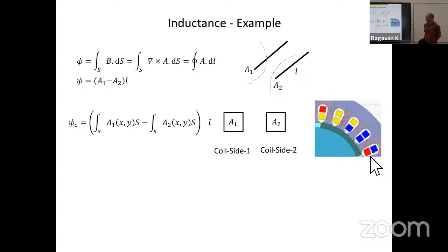Similarly, in an FEA solver, you don't have access to what the solver is doing. It's a commercial package, and you are not generally going into the background code telling it what to do and what not to do, right? What I have seen is that people think the inductance that the default results function gives is the inductance. But if you want to take the values and make a circuit for further analysis, then you should make a separate model, remove the end winding connection there, and then estimate the inductance. Is that clear? Okay.